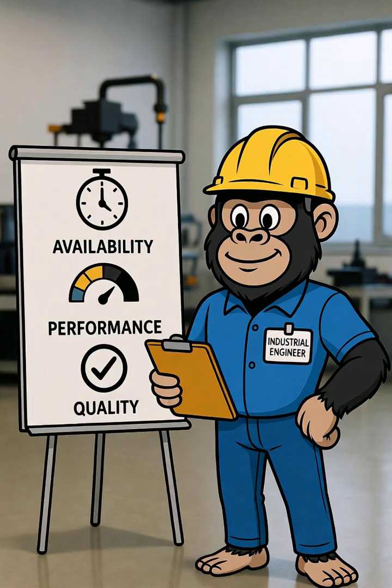First, was your machine actually available and running when it was supposed to be? That's availability. Second, when it was running, was it running at full speed or was it going slower than it should? That's performance. And third, of all the products it made, how many were actually good quality versus defective? That's quality. These 3 factors, availability, performance, and quality, they multiply together to give you one powerful number, your OEE